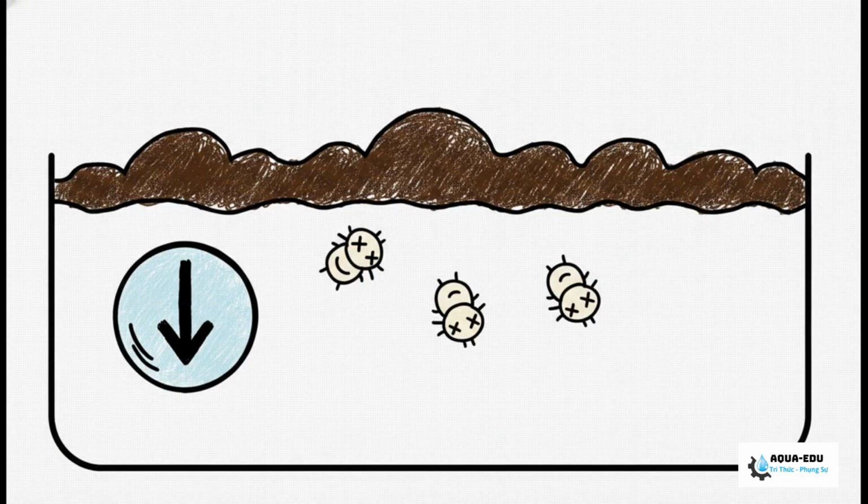Now, the visual reality of a crash is this thick, dark brown foam. Honestly, it is your absolute worst enemy. When you see this creeping up on your aeration tank, it means your dissolved oxygen is totally crashing, and your essential microorganisms, the bugs doing all the actual heavy lifting for us, are dying off rapidly, and all that dead sludge is just floating right to the top. It's a complete biological collapse.